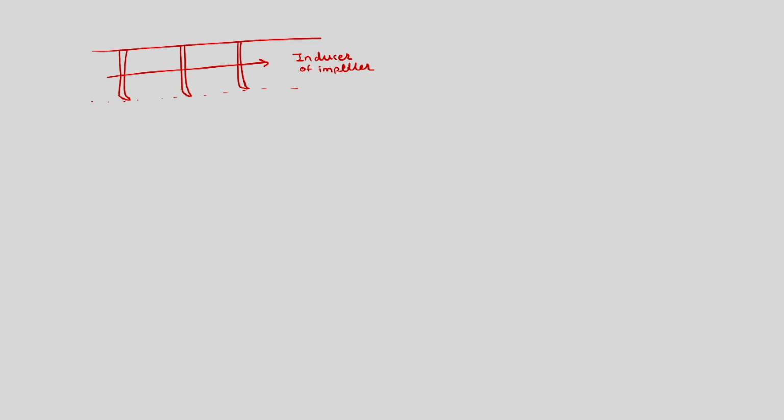We are seeing from the top, and in this case we don't have any guide vane, so we are plotting without IGV or without inlet swirl. For this case air would enter as V1, and this was the inlet velocity triangle.